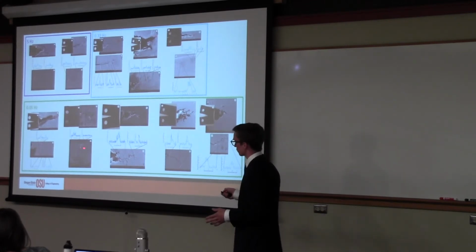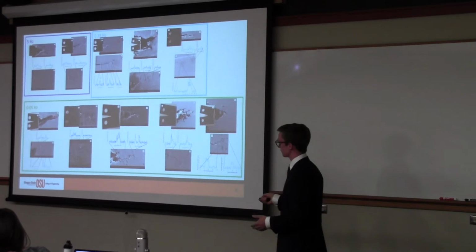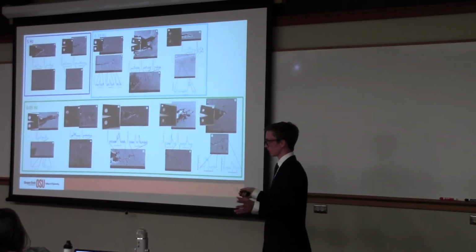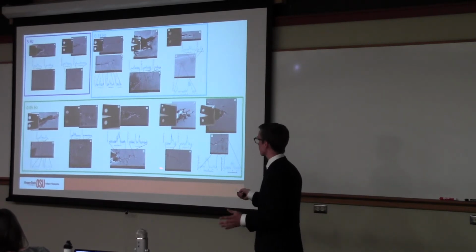So there's a really sharp crack tip here, and then there's this oxide that we detect. There's no oxygen here, and then there's a lot of oxygen here. And same thing with this one. And when you go to higher stress intensities, that protection goes away, for lack of a better word. The whole thing is oxidized.